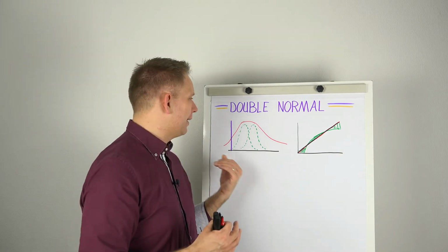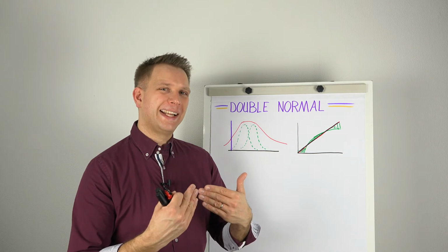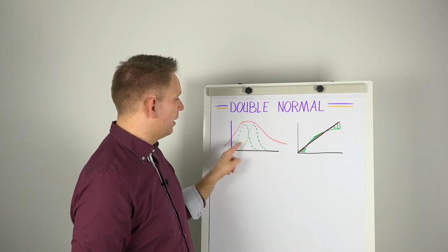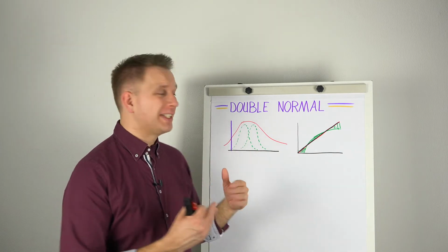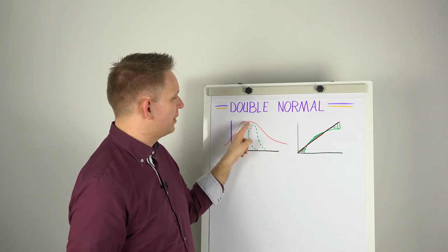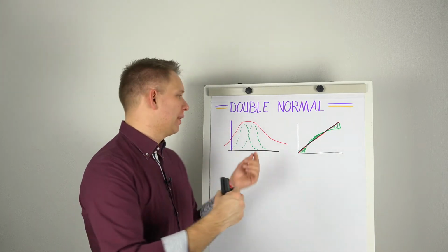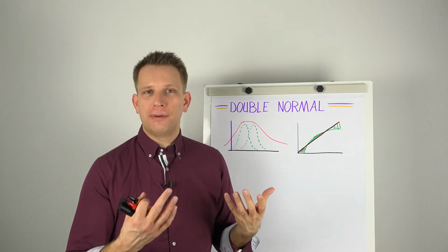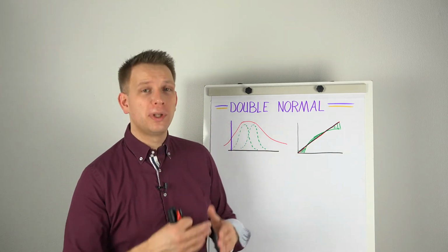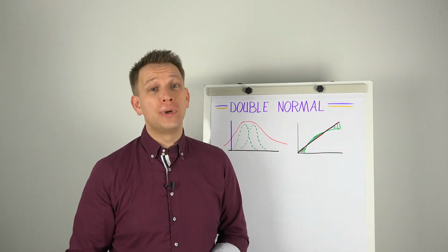And I think that just looking at the economics of it, it might be worth really calculating how much I need to be away from my limit by getting the standard deviations of these individual sites, so these individual nozzles, individual populations, and also the difference in their respective means. And with that, you can have half of the difference of that mean plus 3 times the standard deviation of one nozzle to be your overfilling, your distance from where your limit really has to be.